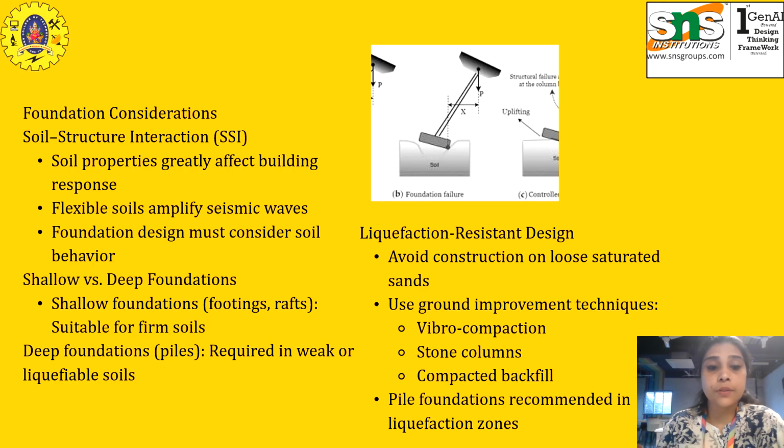Next, I could talk about foundation considerations. If we talk about the foundation, we have to talk about soil structure interaction. Soil significantly affects the building response. Flexible soil amplifies seismic energy. Foundation design must consider soil behavior, settlement, or tilting. Shallow or deep foundation?